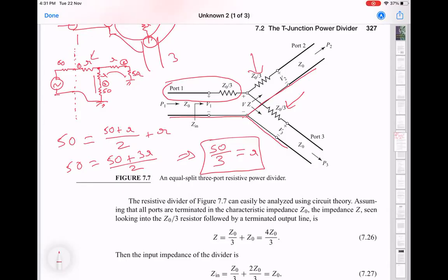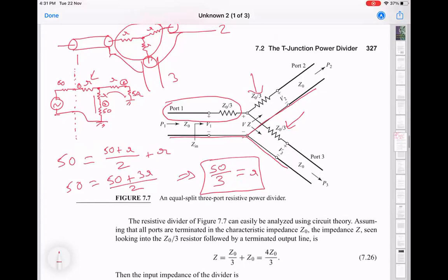What we are trying to find out is, what does a circuit which is drawn here do? I mean, we started with the idea that this is a power divider, and it's a lossy power divider because I've actually used resistors in its construction, and those resistors are going to dissipate energy, which means it's not going to conserve power in terms of just the ports, what comes in and out of the port. So in order to construct that device properly so that it performs the operation I'm doing, I'm now going through some calculations to figure out what is the correct way to do it. So the first condition I have assumed is that I want everything to look matched.